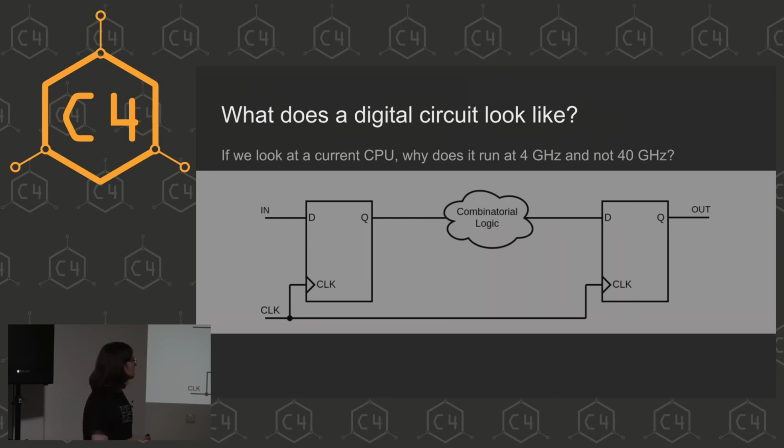then it switches to the output. At the same time, the value that has been calculated by the combinatorial logic in between is already here at the output flip-flop. So when the clock edge rises, both of these flip-flops will hand the value at D over to the Q output. And so we get basically the result of the combinatorial logic calculation on the output, and at the same time, the combinatorial logic circuit is being fed with a new value to calculate through this flip-flop.